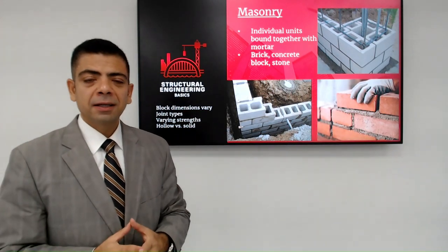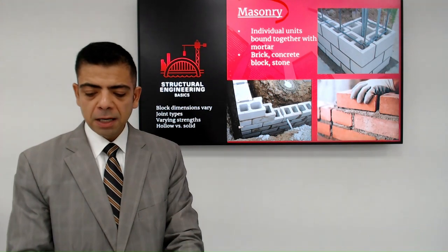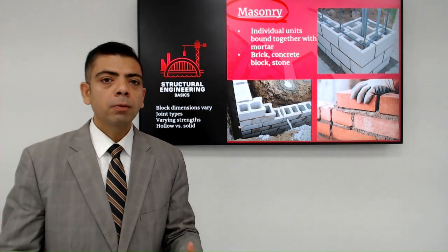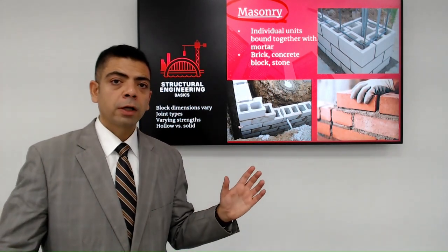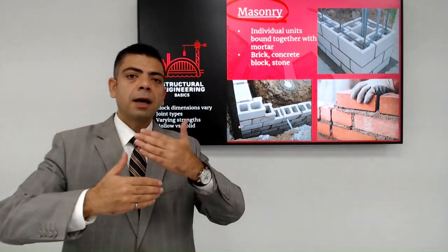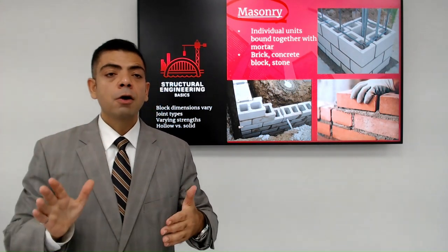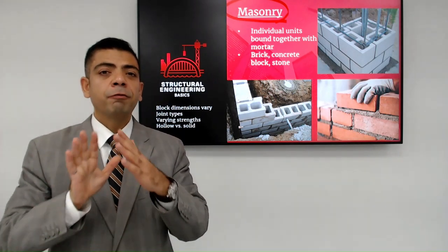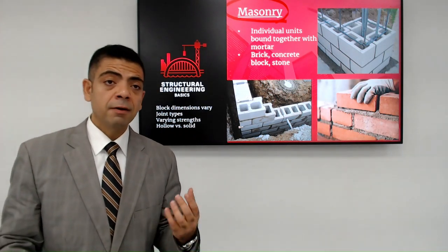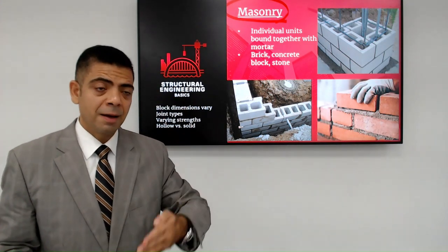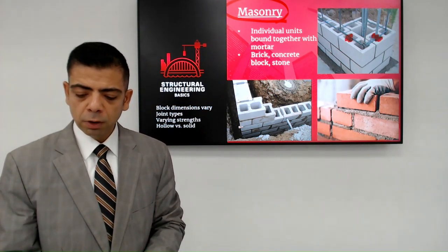All right, this is the fourth type of material, which is masonry. I mentioned it is almost like building with Lego. A lot of builders like working with it because you can gradually build the wall, skip the heavy cranes to move precast, or all the labor-intensive formwork for cast-in-place, and you can still get fairly good bearing resistance out of it, especially if you start filling these cores.